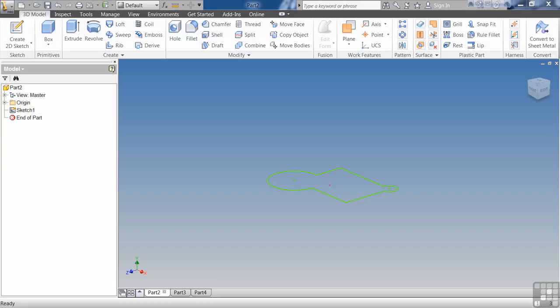In this exercise, we're going to be discussing creating extruded features. Use the Extrude tool to create extruded features from existing sketch profiles. Sketch extrude features require an unconsumed and visible sketch to be available. If the sketch contains a single closed profile, that profile is selected automatically whenever you start the Extrude tool.